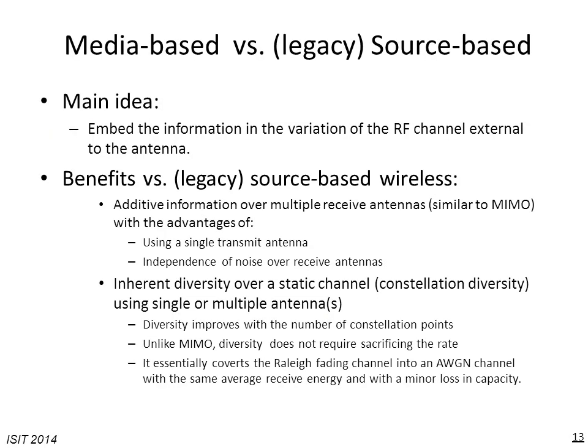To continue the discussion, here I have a slide that explains the benefits of media-based modulation versus what we have known in legacy systems, which I am calling source-based modulation. As mentioned earlier, the main idea is that the information is embedded in the variation of the RF channel external to the antenna.